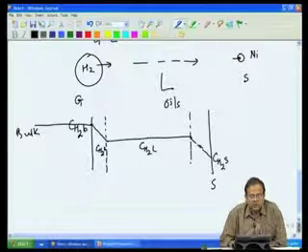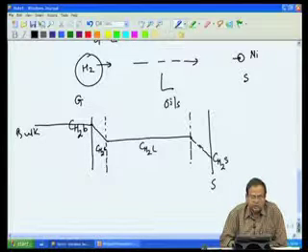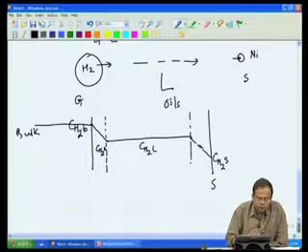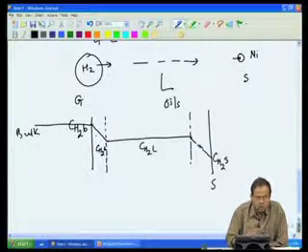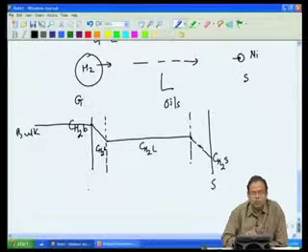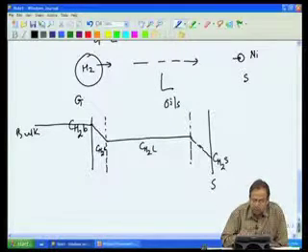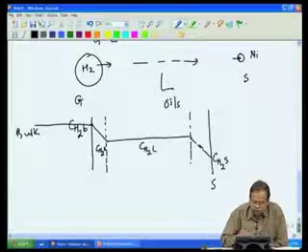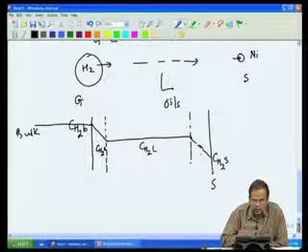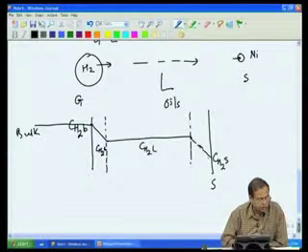So, once again I repeat, we have two interfaces, gas liquid and liquid solid, and therefore two mass transfer resistances, namely from the bulk gas to the bulk liquid, all mass transfer in this thin film. Bulk liquid transport or mixing is good, so we do not assume any further drop, but from the bulk liquid to the solid, the entire mass transfer is in this boundary layer, and we have concentration C2S.